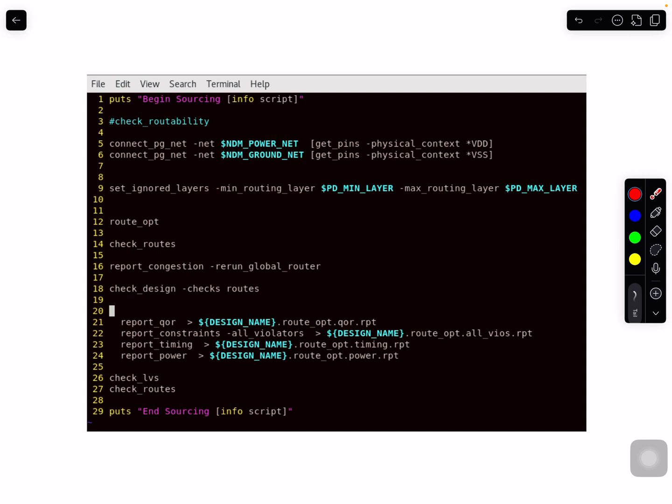You can do that. Or maybe you're working at a block level, and your design will eventually be an IP used inside another SoC. You can also limit to certain layers, so that at the SoC level they can route on top of your IP on certain metal layers because you're not using them. But if you are using certain metals, the SoC at the top level will not be able to route above your IP. So selection of this can be important in the context of your projects or design.